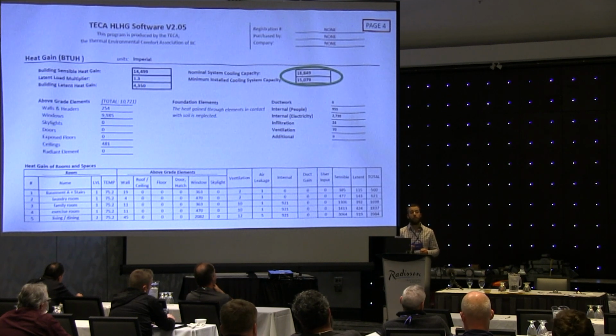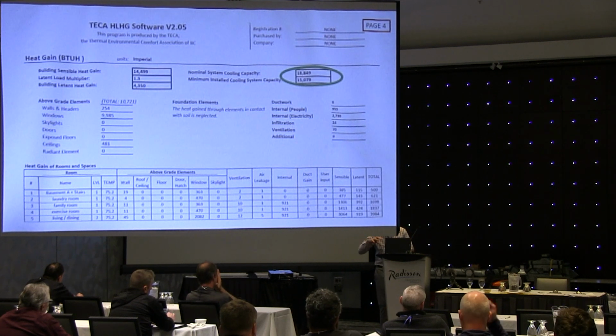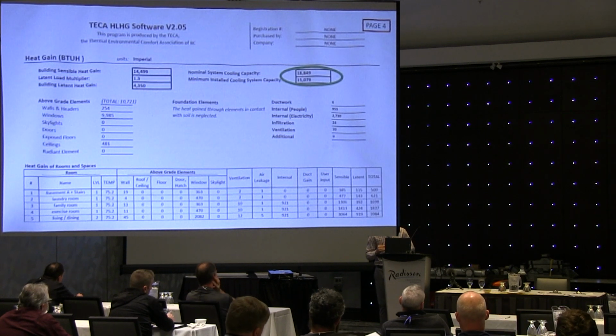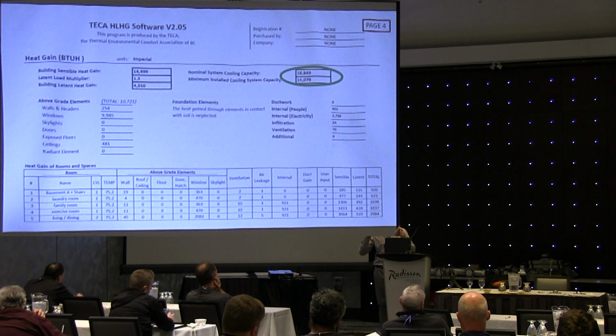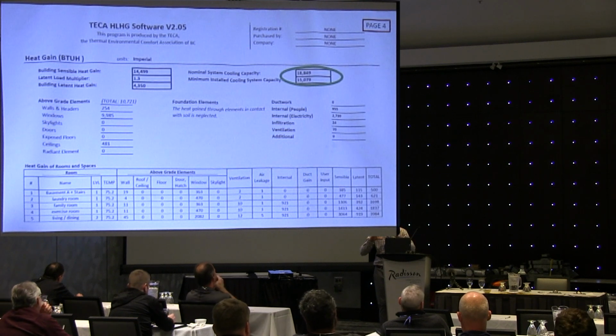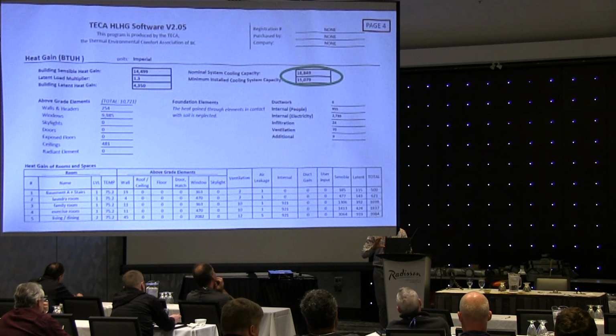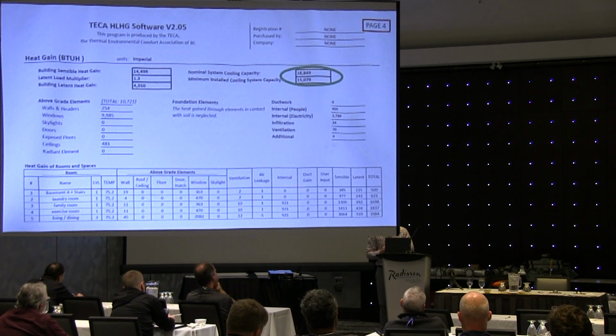I can't tell you the answer, but I can estimate that it would still hold true, because the way that would get accounted for is when I calculate heat loss and heat gain through that window, my latitude and my longitude. Within the calculation for window heat gain, it's fairly complex. It considers latitude, longitude, everything like that. And so that is where it's going to be considered when I calculate the worst case scenario gain for that window. But the same dynamic is still going to happen. The sun is still only in one place at any given time.